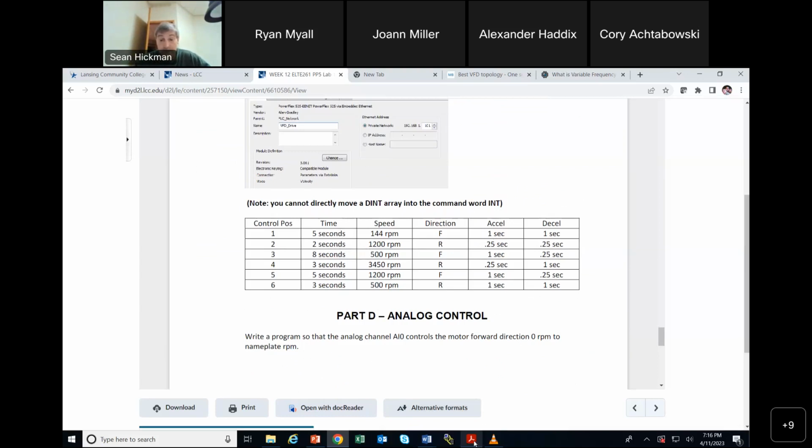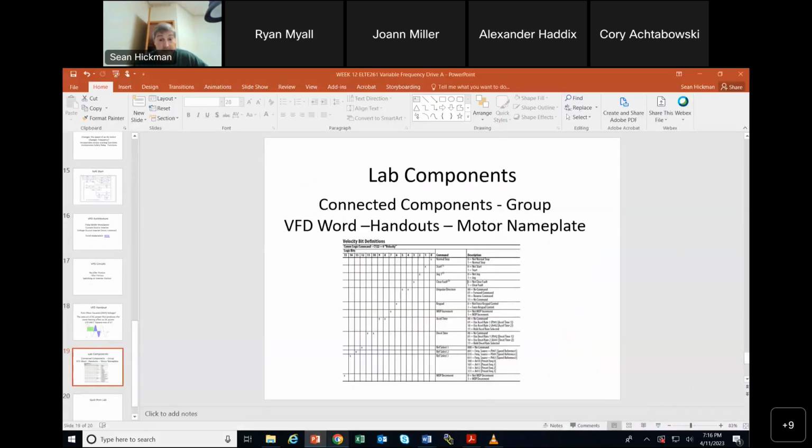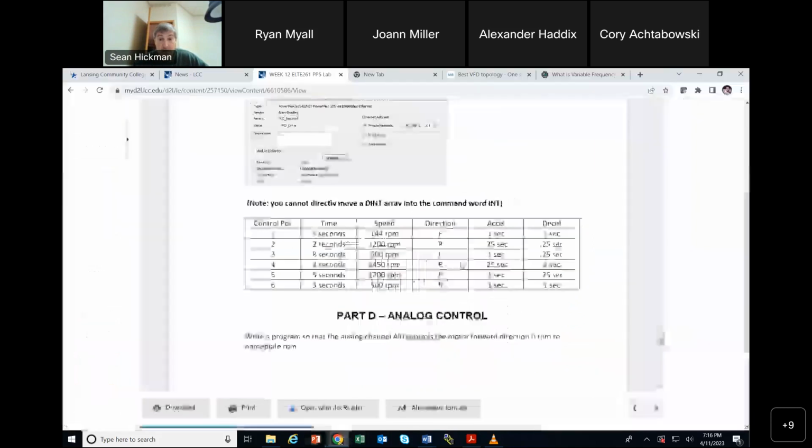And how do you get all that? You come here and some combination of 1011010101 matches up to all those properties. And here is the command word. So for each one of these cases right here, you want to write down the 16-bit word, is what I recommend. And then like I said, I like to convert it over to decimal so I can just pump it into the sequencer. All right, so does that make sense, on a scale of 1 to 10, that this is represented by a word? And that's the first part of the sequencer.